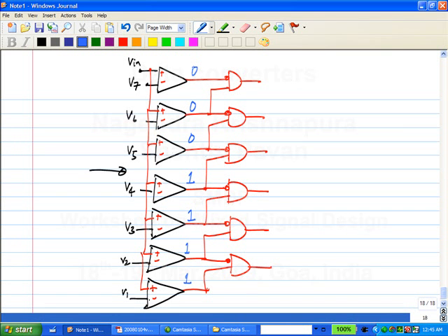Yes. Right? So one thing we observe is that the output of the comparators will be a string of ones followed by a string of zeros, and where this transition from all ones to all zeros occurs is where the input lies. Does that make sense? Okay. In other words, if the input is low, the height of the ones column is small, zeros become large. If the input is large, the height of the ones becomes high.